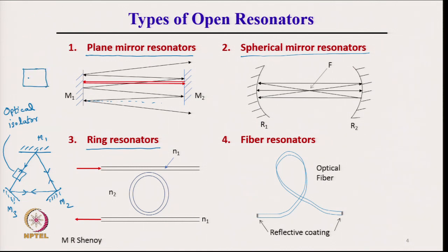Its symbol is an arrow showing like this, which means light entering from here would pass through, would be allowed, but light which is coming back in this direction will be blocked, and that is an optical isolator. So, if we put an optical isolator, it is possible for us to have ray paths only in one direction, travelling like this. That is an advantage of a ring resonator.